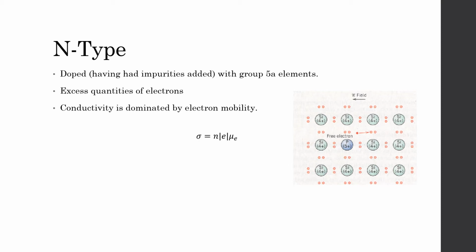This allows it to freely explore the crystal lattice that it's in, allowing it to dominate the conductivity equation. In this case, conductivity is equal to the number of electrons times the charge of the electron times the electron mobility.